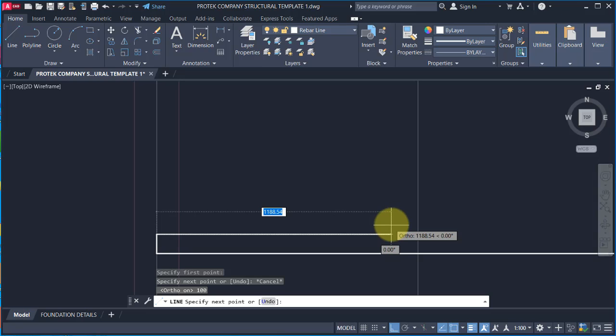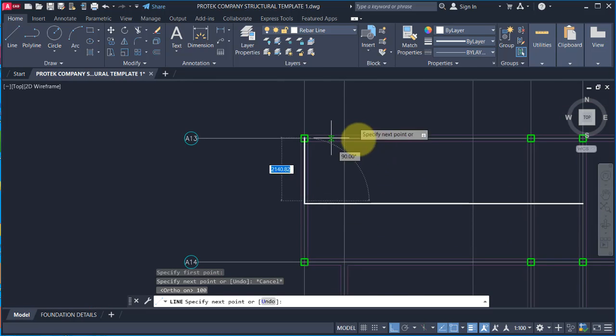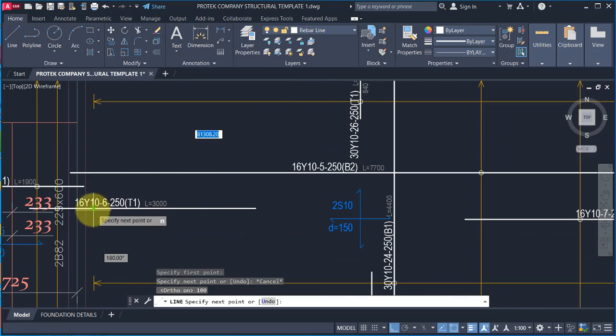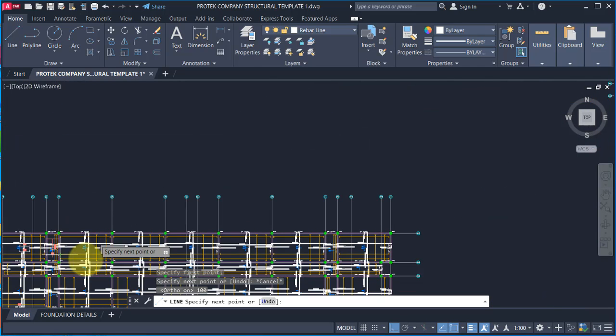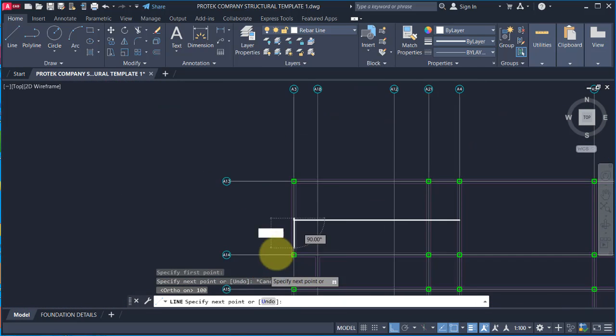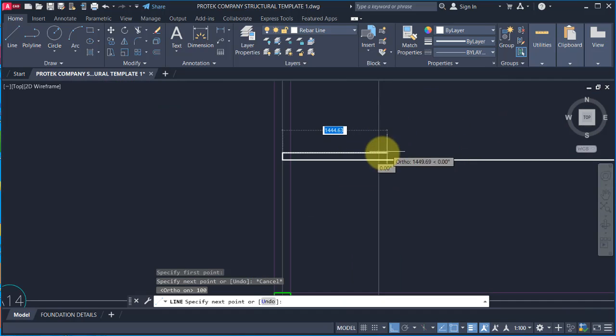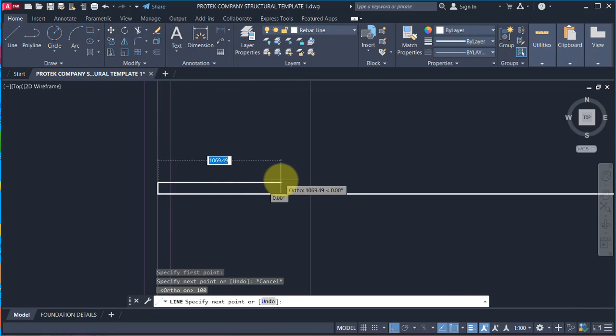The minimum length you should have going this way now is just 50 times D. D simply means the rebar diameter. So, for instance, the rebar diameter we have here is 10. But Prota gave us 10 for the sake of unforeseen circumstances. You can decide to use 12. So we are going to be considering a rebar diameter of 12 millimeter for our bottom bar. Then we can use 10 millimeter diameter of rebar for our top bar.